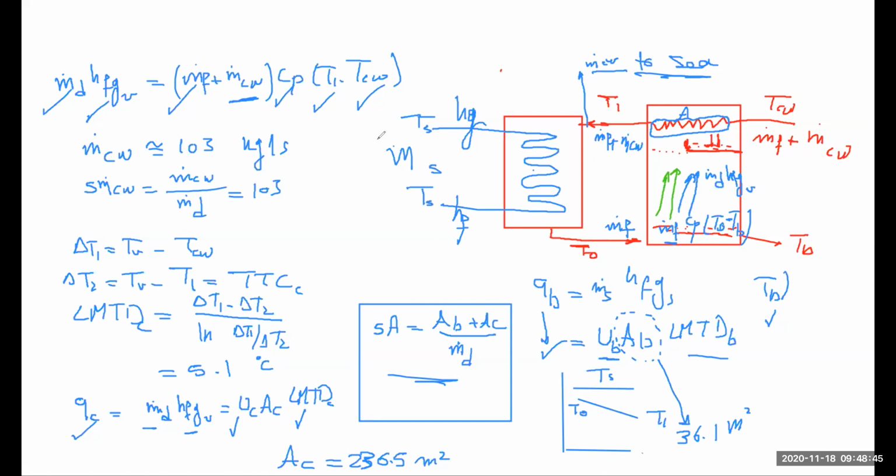Titanium has a very good resistance to erosion and it does not corrode, and that's why it's used at high temperatures. When the pipe is attached to the heater or the source of heat directly, which is the best, titanium or copper nickel? When it comes to higher temperature, titanium is the best. At higher temperature applications, titanium is the best, although it's much more expensive, but they have to do it just for longer life.